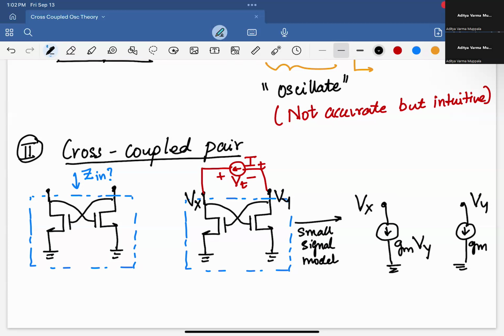And then I have my current source out here, IT, and the voltage across it is Vt. All right. So it's a very simple circuit, of course. All we need to do is to find out what is Vt over It, right? And it's literally two lines. So we know that Vt is Vx minus Vy, and It is nothing but Gm Vy, right? It's three current sources in series, so they must be equal.